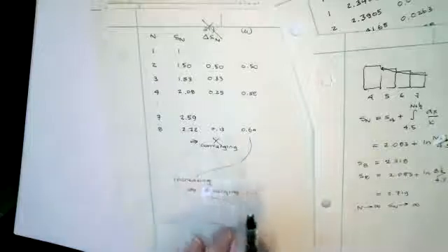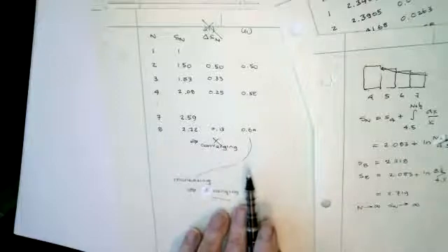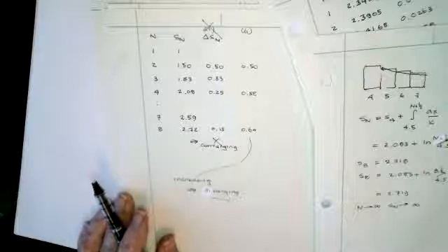Whereas when you multiply by a factor of 4, or a factor of 8 in 3D, you are really changing your mesh a lot. If it starts to say the answer is not changing, it is converging, because you're changing that mesh a lot. Right. Okay, that makes more sense. So basically, the more you change the mesh each time, if your stresses aren't changing because of that, that means you have an accurate model. It really is converging. That's right. Yes.